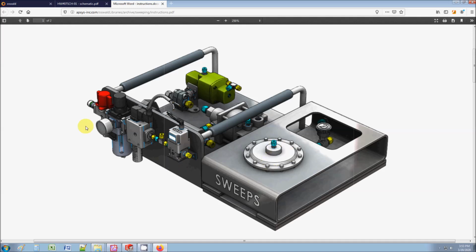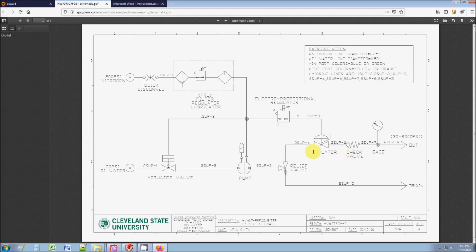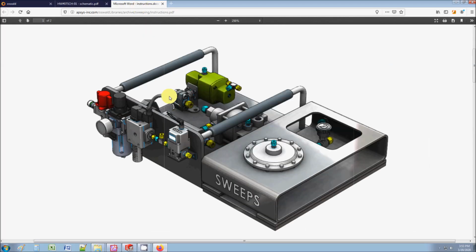This is just a regulator. It's the same thing as this, but it's used for higher applications. Okay, it's right here. It's used for higher pressures, I mean. Okay, so sometimes when you need to work with different pressures, different temperatures, you need to look at a completely different catalog, and your supply options are going to be so much less. Sometimes you have to search the entire world just to get a regulator for like 20,000 psi or something like that. Or you have to custom design it because there's just not a lot of companies that can deliver that specification. So anyways, this is a regulator that are rated to 10,000 psi, so this is why we have that.